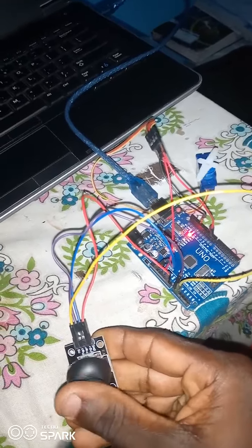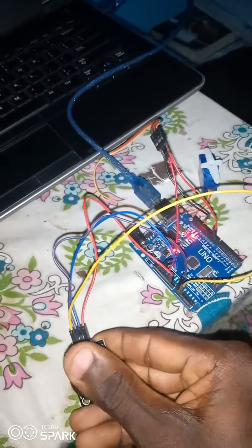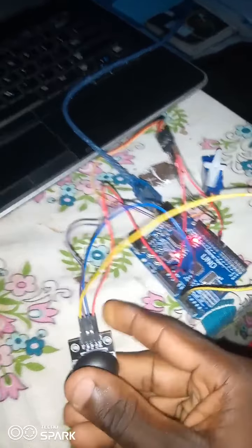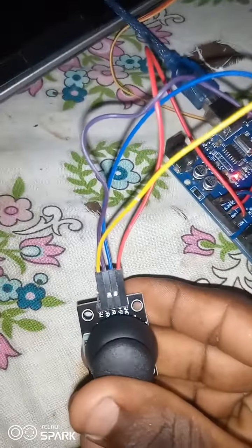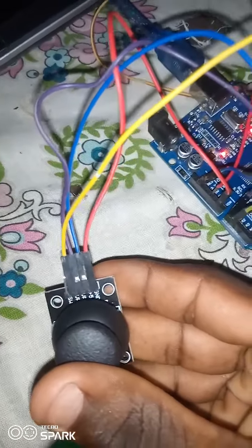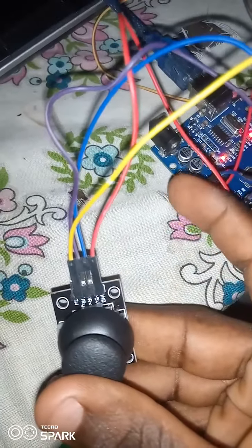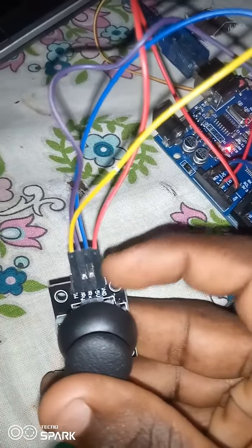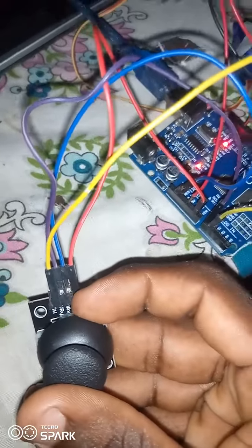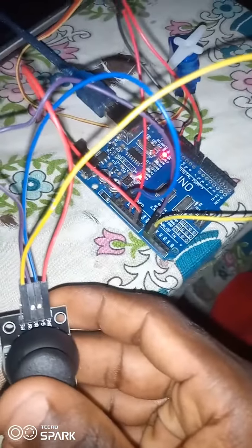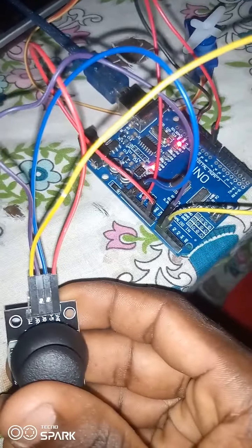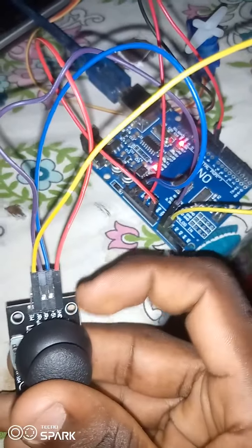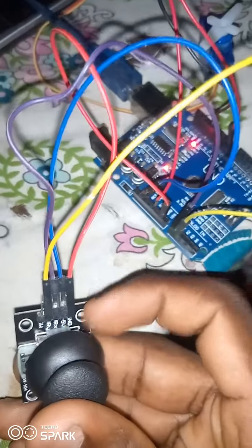Thank you guys very much for watching, but I'm still going to make a recap, an explanation again, to make sure it's okay everywhere. Like I said already, here is a joystick. It has GND. GND goes to ground on Arduino. 5 volt goes to 5 volt on Arduino. RX goes to what we specified in our code, that is A0, and RY goes to what we specified in our code, that's A1. That's where the connection is done.